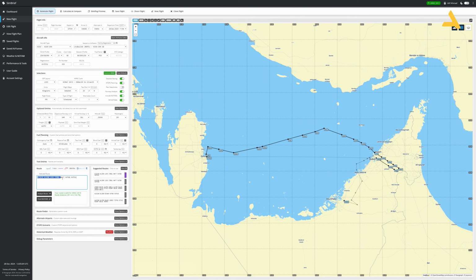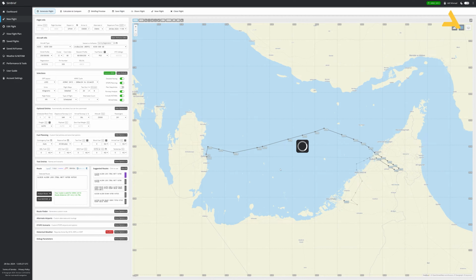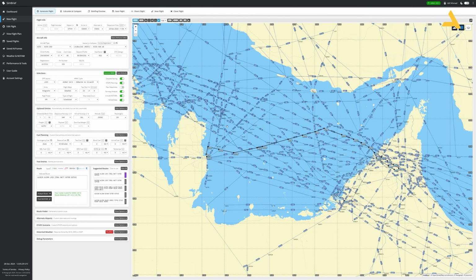Now this flight plan has got different parts, or rather 4 parts. One is the SID, the starting point is the SID, which is standard instrument departure. And the last one is the STAR, which is standard terminal arrival. And then you have the airways and the waypoints. So alphabetical values are the waypoints and alphanumeric values are the airways. You can look at the airways from this option, and then you can see all the airways are visible.